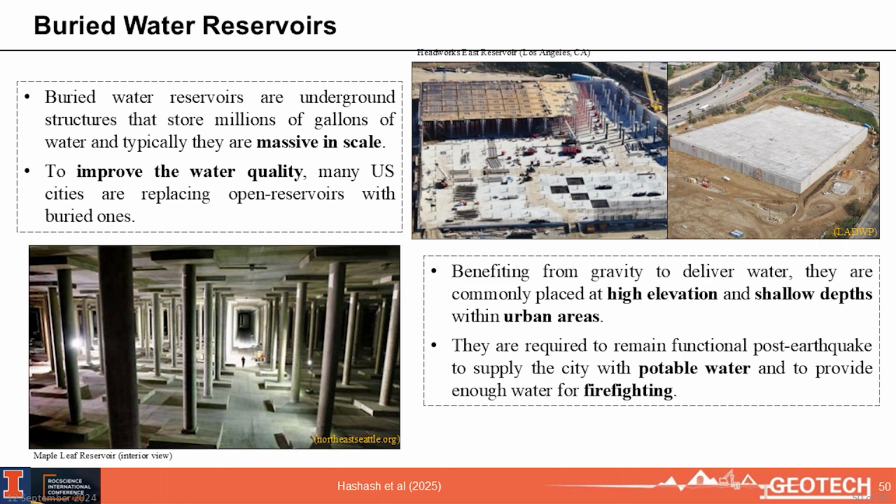Water reservoirs are important. Well, you want your city to have water after an earthquake event. More importantly, you need water to fight fires that happen after an earthquake. So that's critical. And what motivated this work is that engineers building one of these reservoirs in one of the cities somehow overlooked the seismic design. They were doing all their evaluation in 2D. And I will tell you that it turns out that the response is 3D, which we didn't understand before. Hence, why we need to do 3D soil structure interaction.